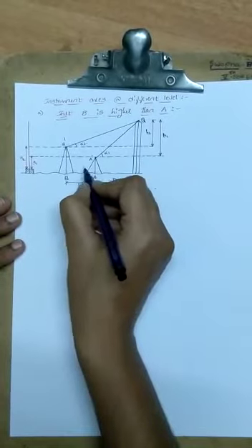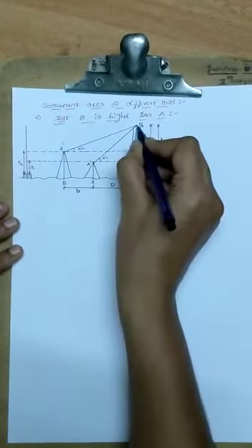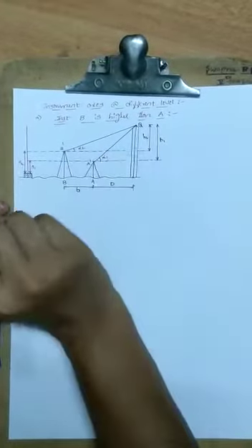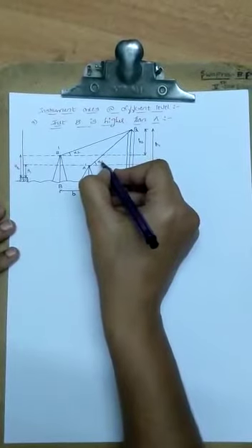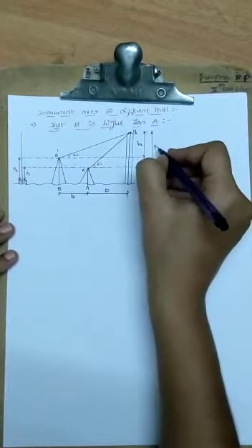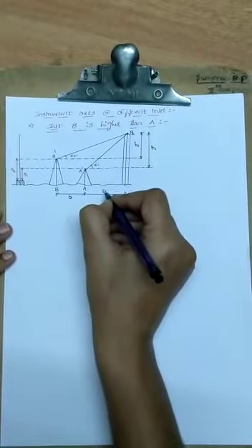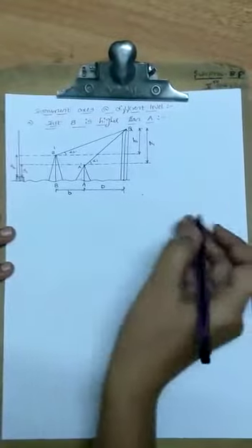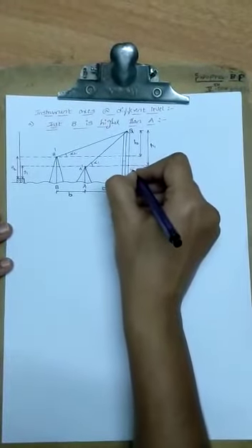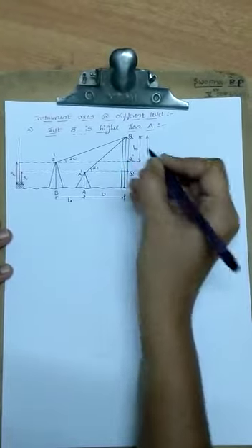Next, you need to shift the instrument to the B point. Then bisect the object Q and take down that vertical angle reading, that is given by alpha 2. Okay, the initial data you need to consider is alpha 1 as well as alpha 2. In this case also you need to calculate H1 and H2 value as well as D value. In order to derive that, okay, the same procedure, consider a triangle, call this point as Q dash and this point as Q double dash.